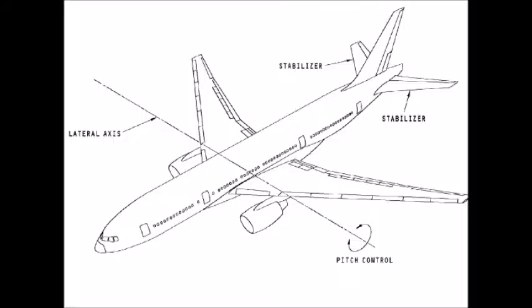The purpose of the elevator assembly is to supply short-term pitch control of the airplane. The elevators are lightweight composite material structures. The skin is reinforced with graphite bonded to a core of Nomex honeycomb. The overall dimensions are approximately 70 inches by 403 inches. Each elevator panel weighs approximately 337 pounds. The elevator attaches to the stabilizer rear spar with 7 hinges.